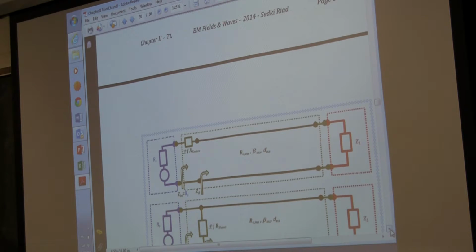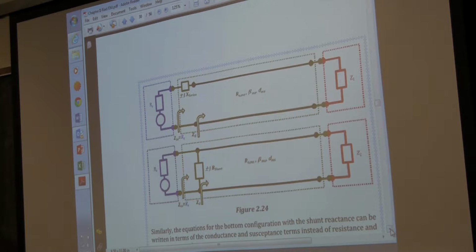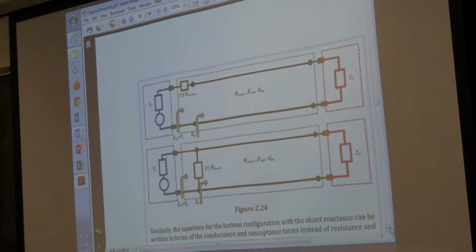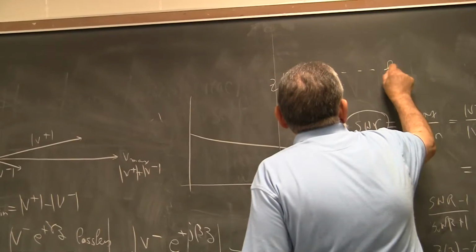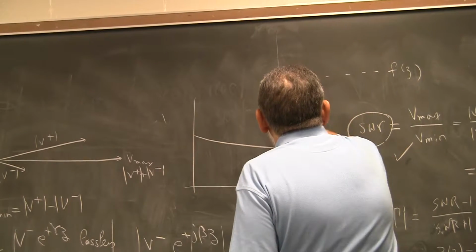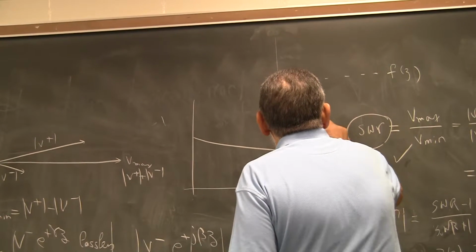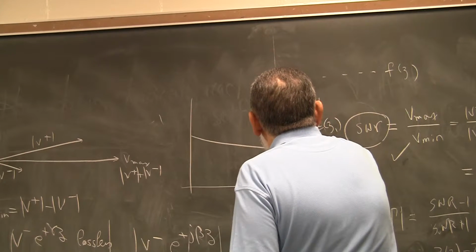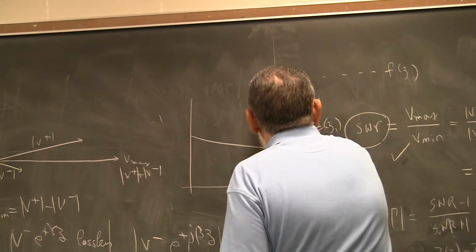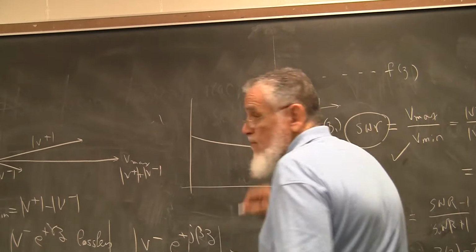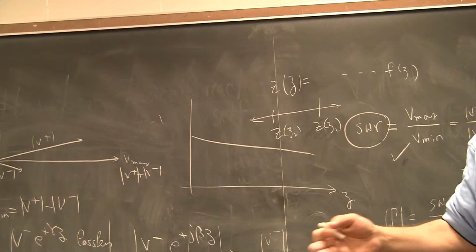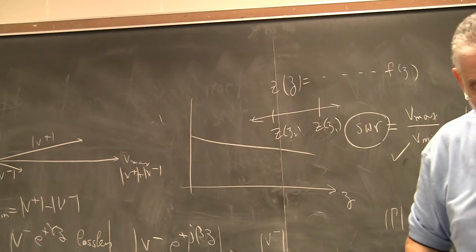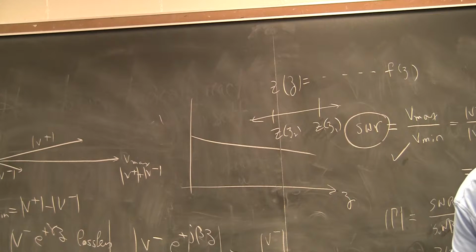So what we do is we use transmission lines to play the trick. If transmission lines have a varying impedance as you go from one place to another, Z of z is equal to, and you recall it's a function of z, that means if I go from one place to another, the impedance Z of z1, Z of z2 are different. So I can change the impedance as I move down the line. So if I can change the impedance as I move down the line, why not use transmission lines to provide the impedance level matching that we require?